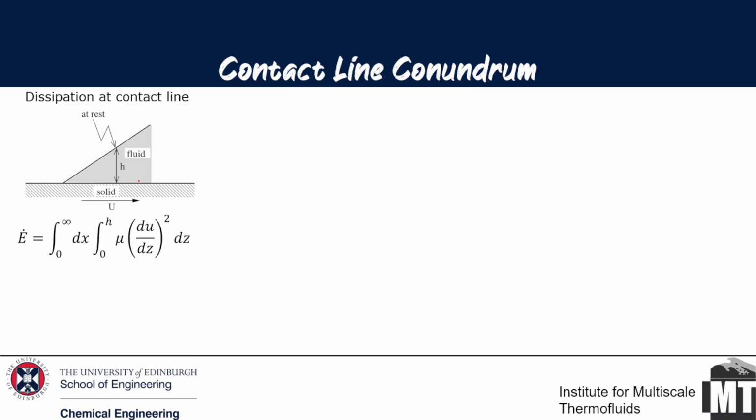And if you have a droplet which suddenly decides to move, it's a bit weird. You have a no-slip boundary condition. Why should it move? It's defying the condition. This is actually called a contact line singularity. This has been a debate for so many years, and I should say that it's not yet resolved fully. There are various ways. So that is the flaw of the modeling approaches that we use. Whenever you have a triple phase contact line, you need to have special considerations at the contact line boundary. It is not completely a no-slip boundary condition.